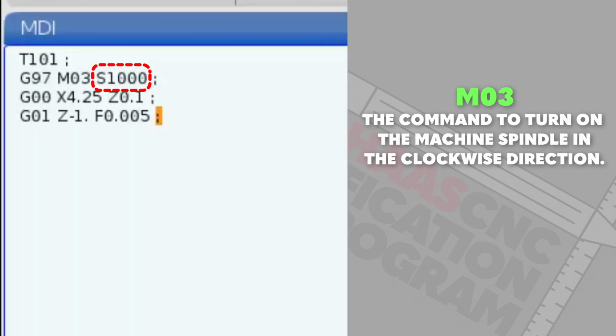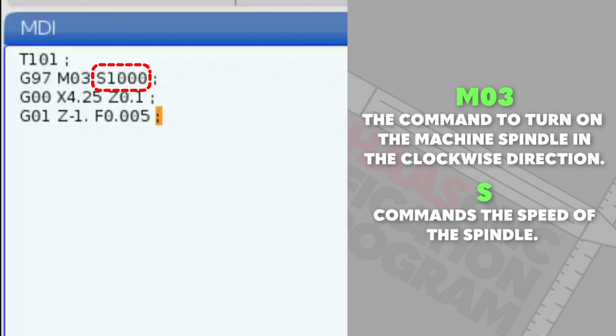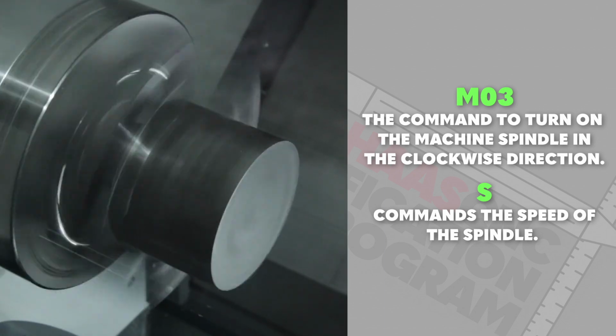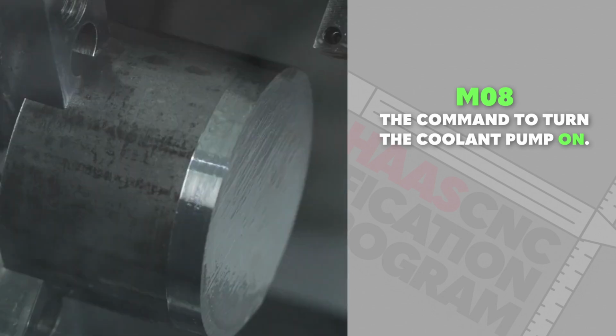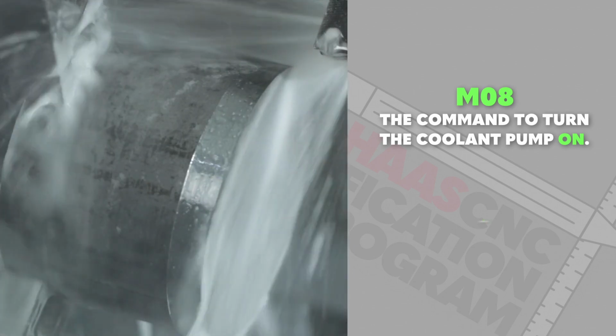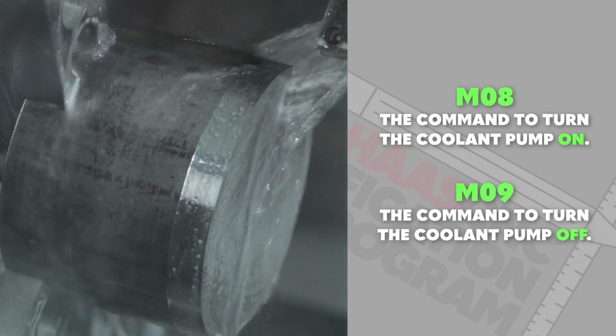The letter address S is the speed command, so we would program M03 S1000 to rotate the spindle clockwise at 1000 RPM. Another M-code example is M08, which is the command to turn on the coolant pump. The code M09 will turn the coolant pump off.